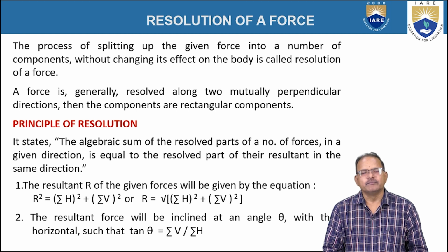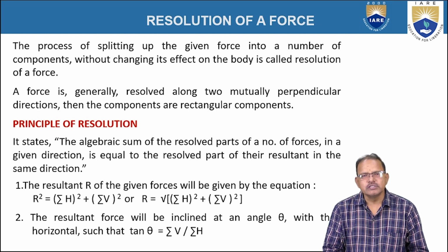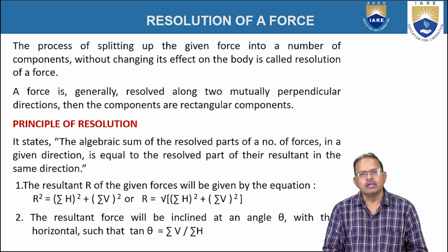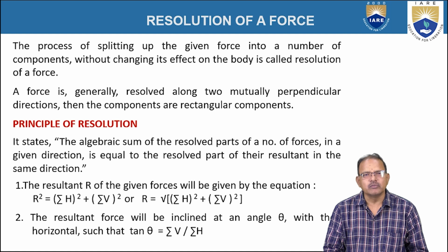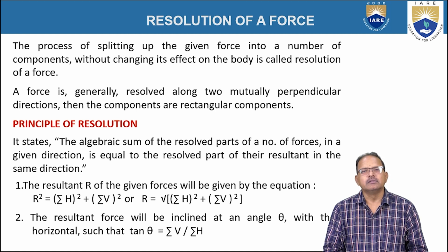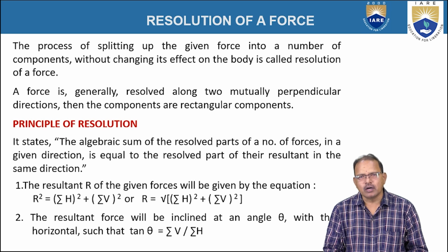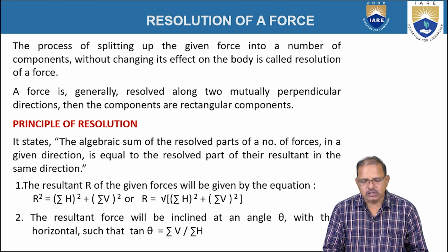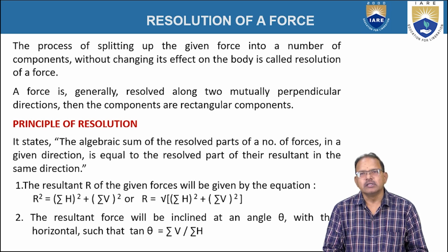In this method, the force is resolved into two components, preferably at right angles to each other, one along the x direction and one more along the y direction. When the force is resolved into two rectangular components, this is called resolution of the force.